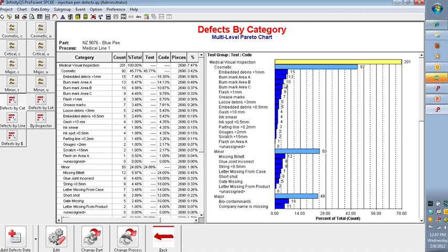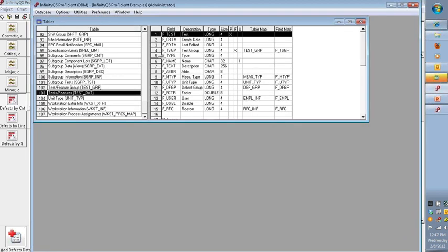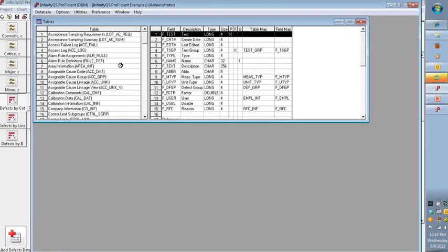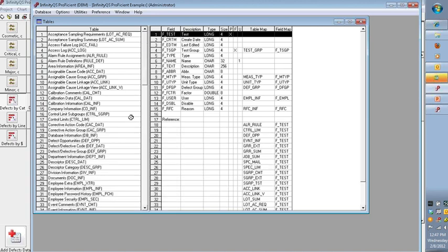Basically, what we've got set up in Proficient, and this is probably a good offline conversation. Julio, if you want to call and talk with one of us specifically one-on-one, that's very possible. But in general, what we've got in the software is the ability to create acceptance sampling plans, where I can specify things like the AQL level I'm expecting, my alpha and beta risk, my lot tolerance percent defective.